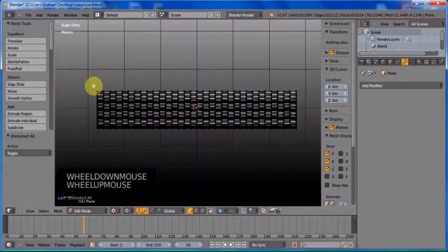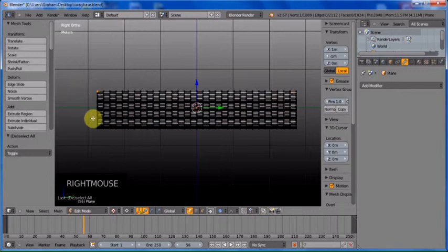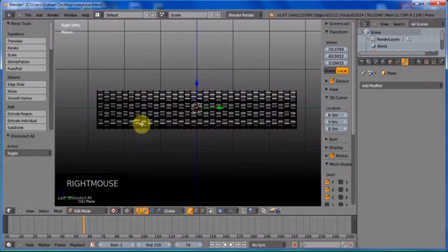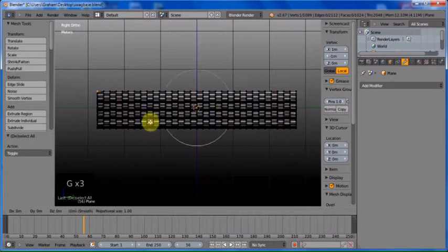So if I'll explain this, if I select this first vertex and I've got my proportional editing on, if I go to move it, okay, so I'll press the M key for move and nothing's happening. Not the M key, G. If I go to grab it, so press the G key to move, you see I've got this white circle. Now sometimes you'll do this and you won't see the circle. It's because it's too big and it's off the screen.